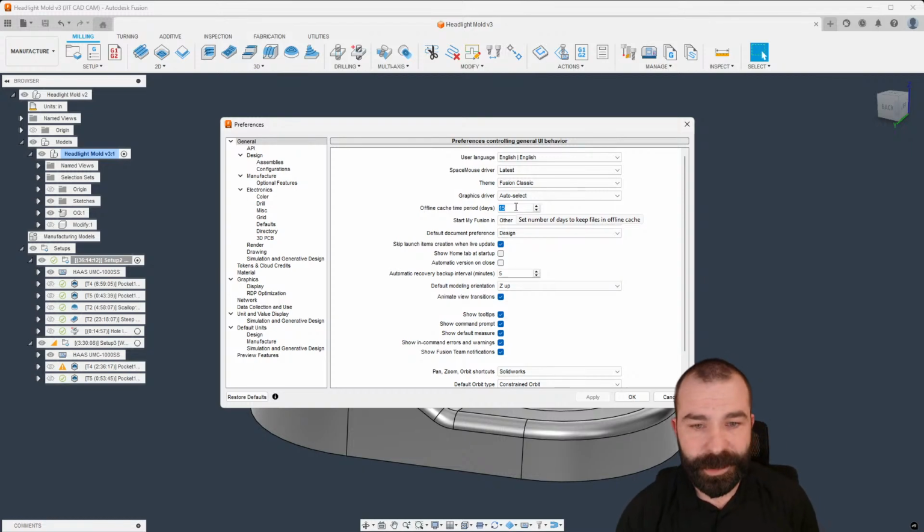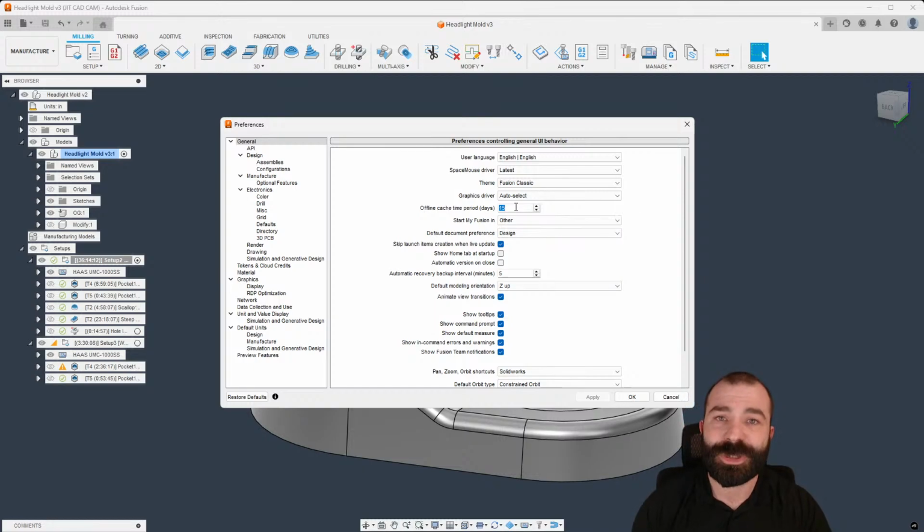I've had several customers lately where the problem resided in a lot of mesh and scan data being uploaded. Because they were holding 15 days, it ended up being, I think, close to 150 gigabytes of meshes. This in itself was their problem: they were almost storing too much local, and Fusion was trying to basically compensate and math all of that stuff in one shot. So a few other things from that, we can pivot.